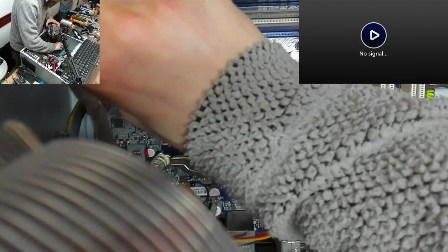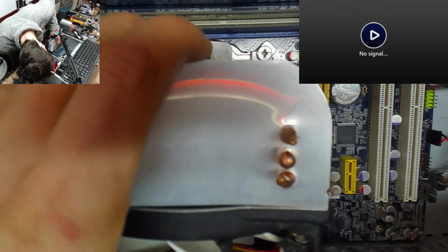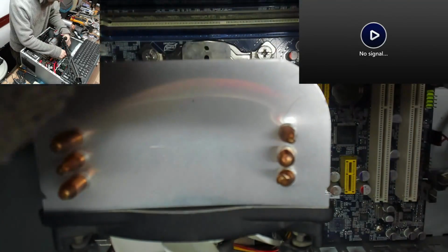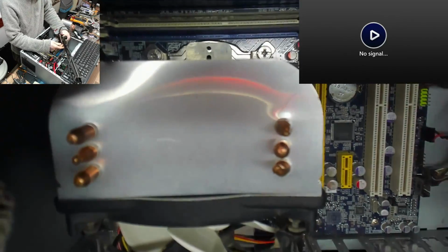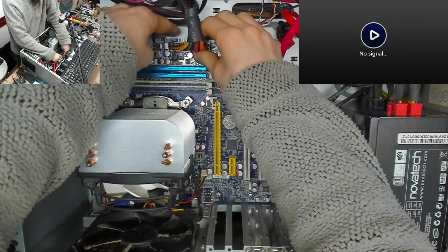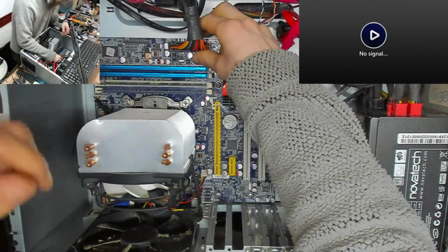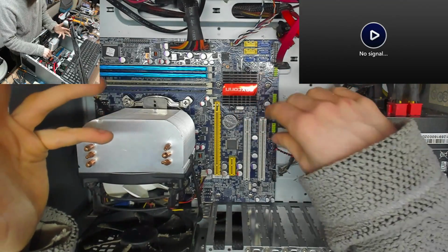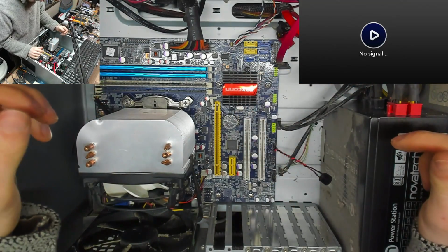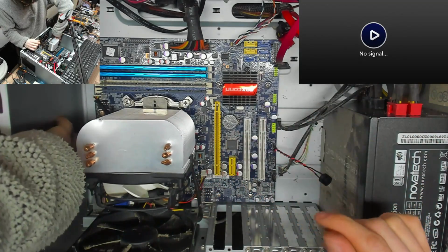So we'll just plug that in. I very much doubt that it's anything to do with the CPU at this stage. I think it's more likely to be a bad motherboard, but we'll see. I'm also tempted to drop down to fewer RAM modules, because we have passed the RAM test, but we might have some of those modules that only work intermittently. When they work, it posts, but when they don't work, it doesn't post. That would also explain our problem. So that is something to consider.